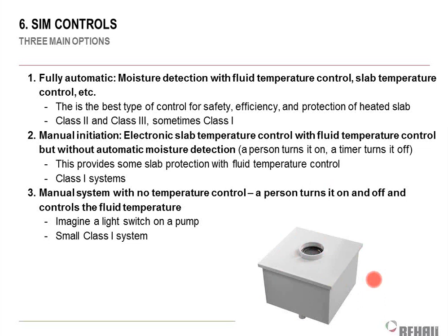And then I got a temperature sensor, an outside air temperature sensor, that says if it's below 38 and I see this moisture sensor, it must be snowing. If I see the moisture sensor and it's above 38, it's probably raining, not snowing, so I don't care, right? So it's got to be cold and wet, and then we turn it on. That's a common one that we use. You can also use the slab sensor ones. I'll show you a picture of one of those in a minute. We lovingly call them the hockey pucks. You bury them in the concrete. But the one we're showing you here, you can just put on the side of the concrete, behind a bush, something like that.